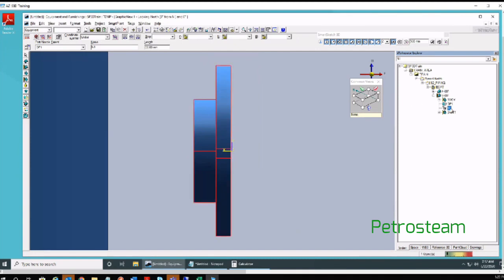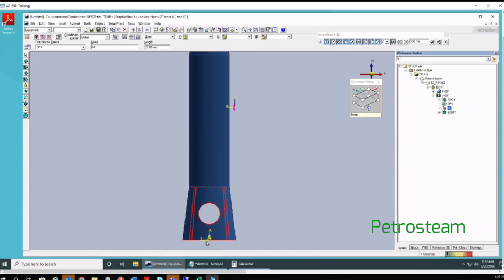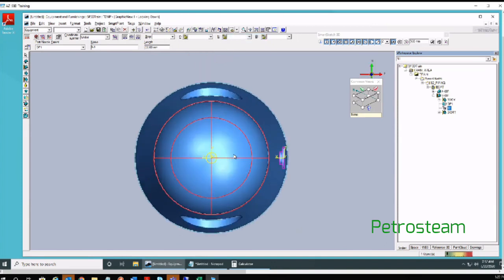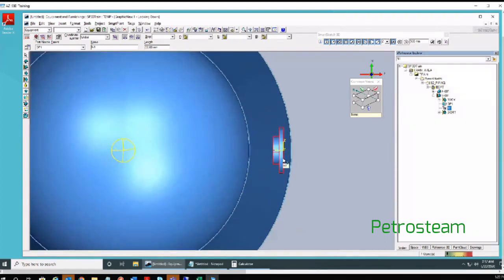You can see, you can fit it. Already the nozzle N1 is selected. The distance, this will be from here, it will be 5 meter distance. N1 value we have given for position and face of flange. Now I will show you in top view the face of flange for this nozzle from the center of the cylinder or from the center of this DP point. DP point, it is 750 plus 200 outside projection of this face of flange. Okay,